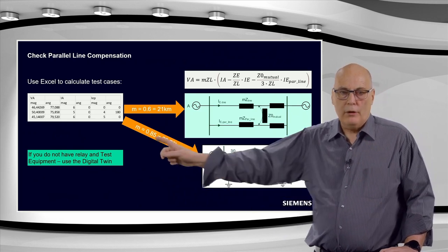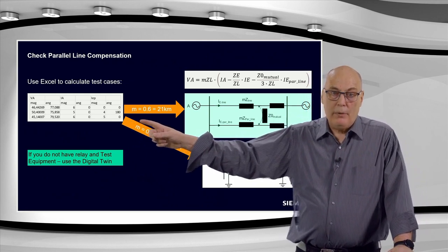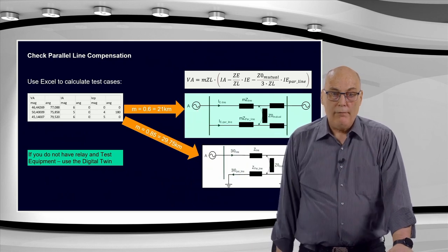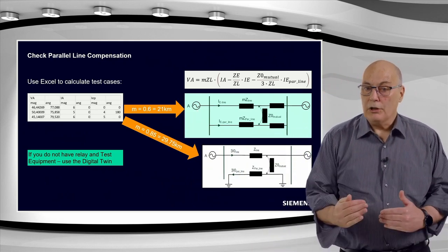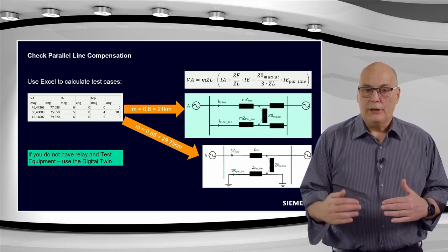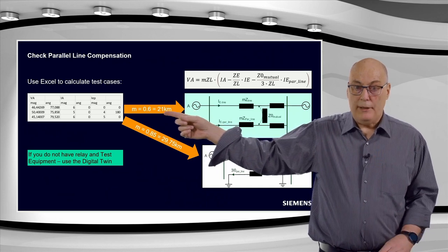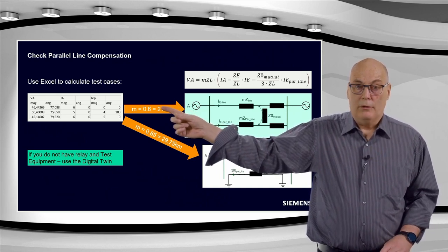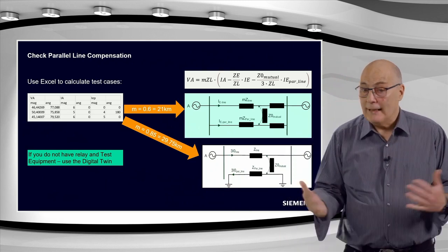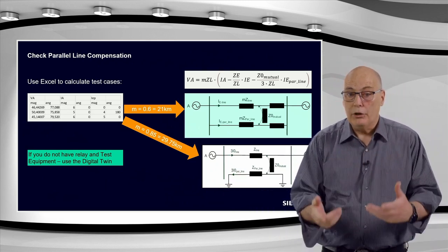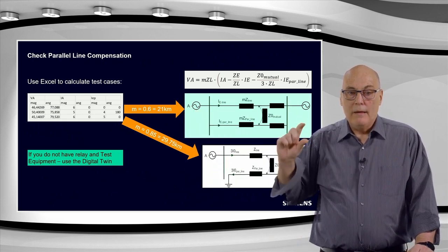And it's interesting, if you look at the voltage magnitude, although the third test here has 6 amps and 5 amps in the parallel line, you can see the voltage on the complete left is only 45 volts secondary for the third test. Although it's larger current, normally larger currents would give us larger voltages. If you compare it to the first test, which was also with 6 amps on the protected feeder, it was 46 volts. So the 5 amps on the parallel feeder actually reduced the voltage. That's what we expect. And that's the risk that this final case can give you an overreach. You can see we have the same current in the third test as in the first test on the protected feeder, but a smaller voltage.